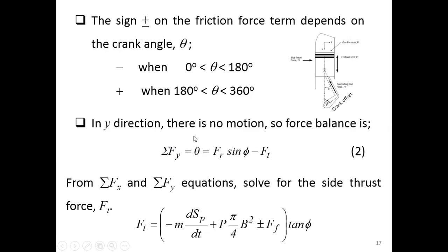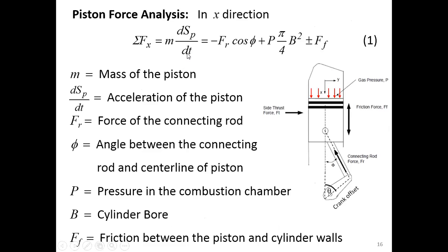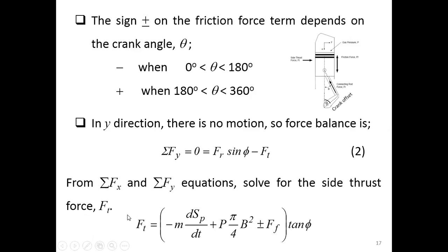By solving this summation of force in the y direction, along with the x direction shown here, you can find the side touch force according to this equation. If you know the mass of the piston, the acceleration of your piston, the pressure in your combustion chamber, the friction force from the behavior of your lubrication oil or the hydraulic shear, and you know this phi,